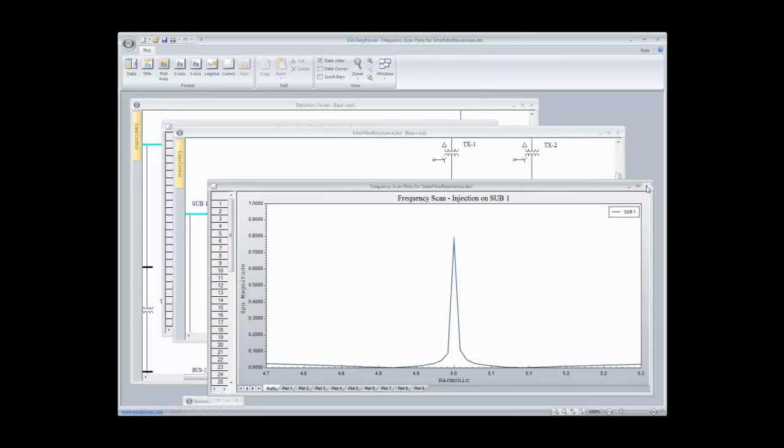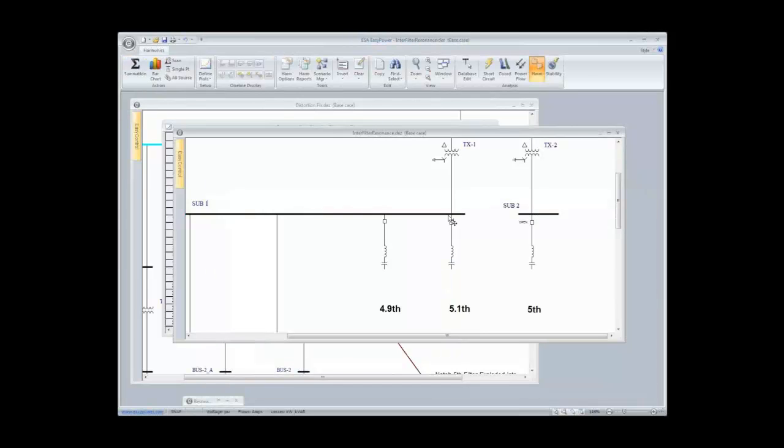Now, what's interesting, okay, I'm making that happen. If you do a distortion, let's put one filter on. You do a distortion, you're at 2.7 with one on. Without it, it's around 9 or something for the harmonic load I have. So with one filter, I got down to 2.7. I put two filters on. Ooh, it goes up, right? Well, it actually didn't go up that severe, and so you might be thinking, oh, well, that's really not that big a deal, until you look at the current in each of the filters.